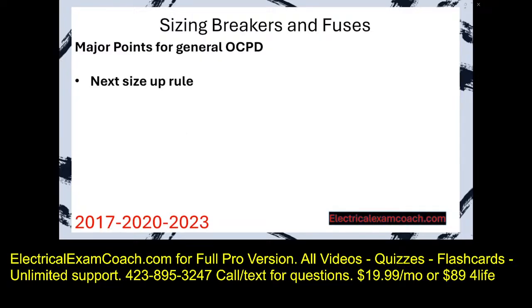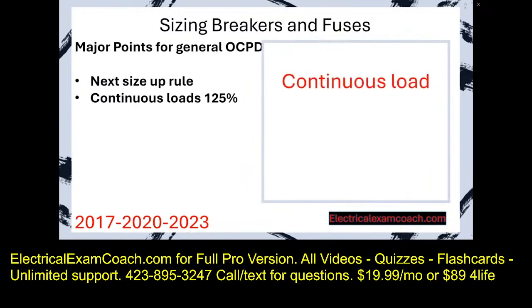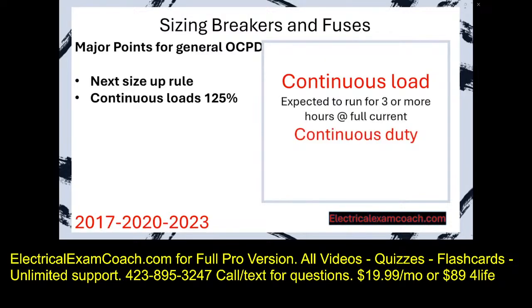The next major point is going to be continuous loads at 125%. There are two different names that you may see: continuous load or continuous duty. A continuous load is defined as expected to run for 3 or more hours at full current. And in the exam prep world, it's going to look like this. You have a load that's known to run for 5 hours. What would the...